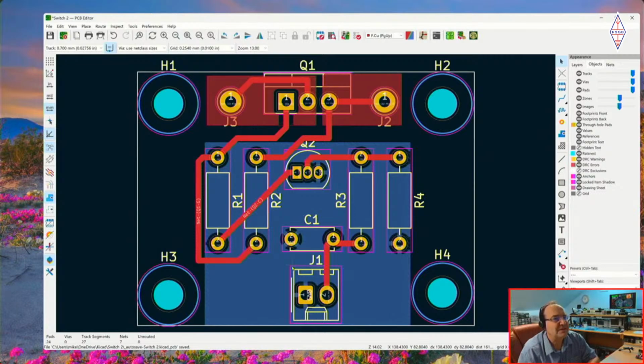The thing about PCB is it takes quite a few square inches to dissipate a watt of power, and this transistor, which is the only thing that's going to be getting slightly warm, has got a big tab on it, so it's generally better to put that on the side of the board and bolt it to a heatsink. But you can use PCB. If something's just getting warm, maybe it's another good use of a bit of copper, isn't it?